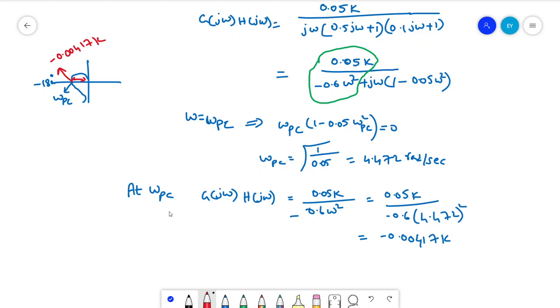Since this is a type 1 system and third order, if you observe, it is actually a minimum phase system, and there is no zero in the system. So in the transfer function we have all three poles, and this is a type 1 system, and we have an order of 3 since there are 3 poles. So we need to evaluate C1 now, to represent it in the G of S and H of S or omega plane.